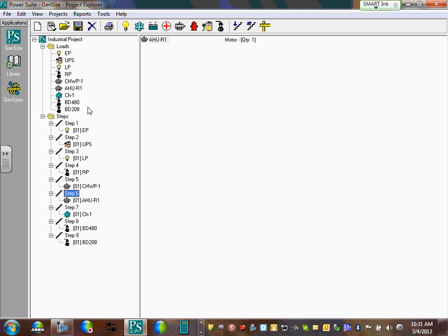Heating load, no, air conditioning is different than heating load. I would use user defined and just put it as 100% heating load. Yeah, heating load, guys, the only thing that you do for air conditioning is just a chiller. Almost everything is going to be motors or receptacles or lights. If it's not any of the above, you can use user defined and just double the value like we did.